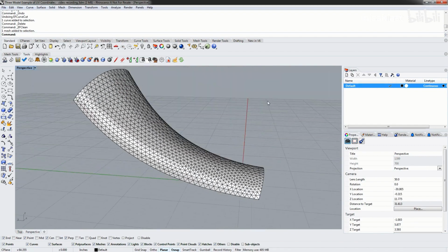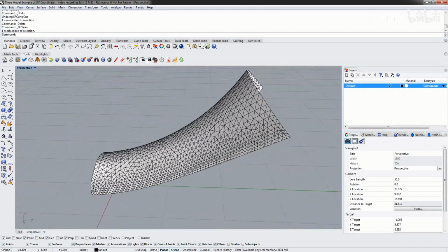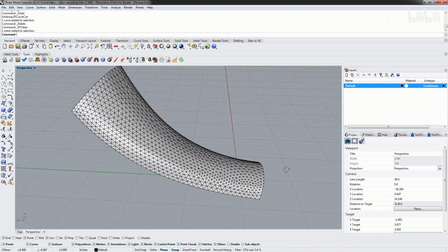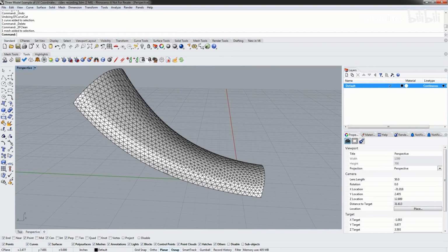To begin, we're going to angle our camera into a position so we're looking at the mesh where we want to create the cut. So for this one, I'm going to create a V-shaped cut right along the surface here. If I create a curve in our viewport, Rhino is going to project it along the axis of the construction plane, which doesn't follow the direction that we're looking at. So the easiest way to solve this is to create a new construction plane, a new grid that is perfectly parallel to the view right now.